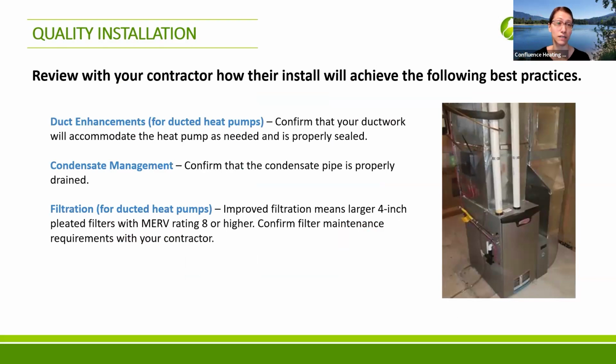Best practice would be to put some silicone or tape at the end, for everyone's knowledge. The copper should never see the air on a refrigerant line at any point, so seal the end of it to prevent that. And anywhere you cut, like to do a bend, make sure you're sealing that for air tightness too. You're not just shoving it in the wall or whatever.